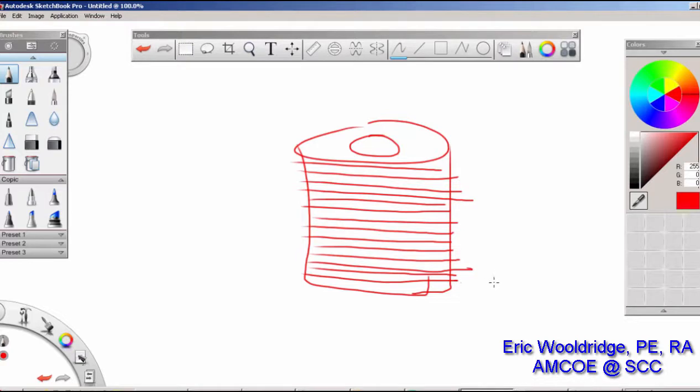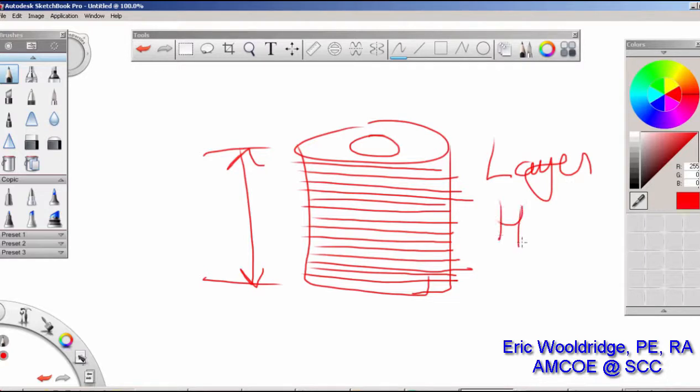So, terminology: slicing. How many slices does it design the part into? Well, that depends on how tall the object is and your layer height. Layer height controls how big the slicing settings are. For example, if the object was 10 units tall and you had your layer height set at 1, it would take essentially 10 slice commands, or slicing sets of instructions. If your layer height was set to 0.5, then you're going to have to do 20 slice settings. Now, you don't actually ever see this.